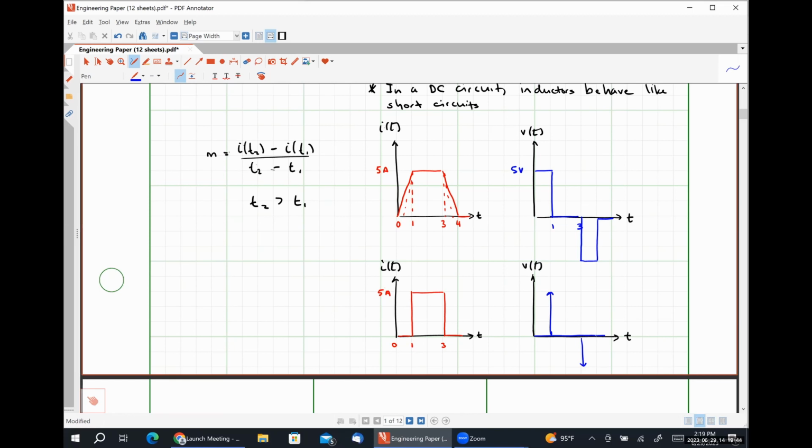Probably. You're 100% right. And there's very much a problem with it, right? So recall that voltage represents the amount of work done moving charge from one point in a circuit to another point in a circuit. So voltage is always dealing with some form of energy transfer. If the voltage is infinitely large for any amount of time, it means that we are transferring an infinite amount of energy, which, as we all hopefully know, is wildly impossible, right?